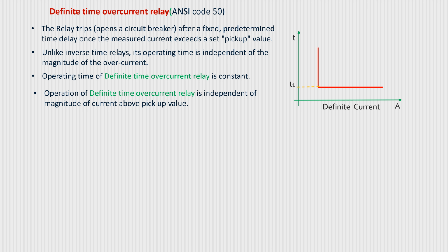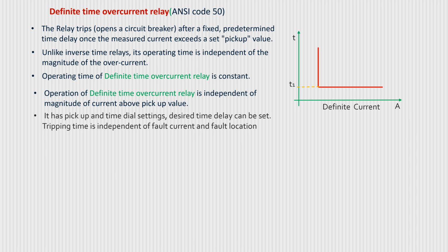above pickup value. It has pickup and time dial settings. Desired time delay can be set. Tripping time is independent of fault current and fault location. Applications: used as backup protection.